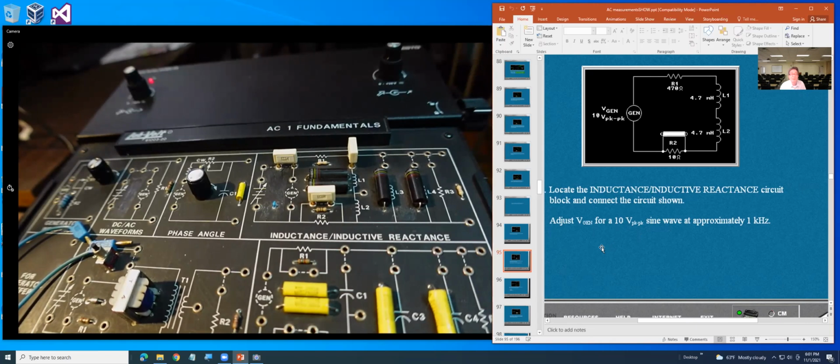And now they say activate the generator at 10 volt peak to peak and a frequency of 1 kilohertz. First thing, I connect the generator output to the circuitry.